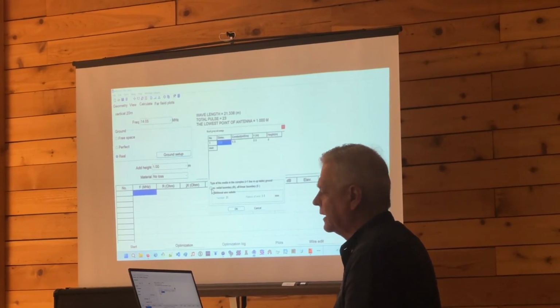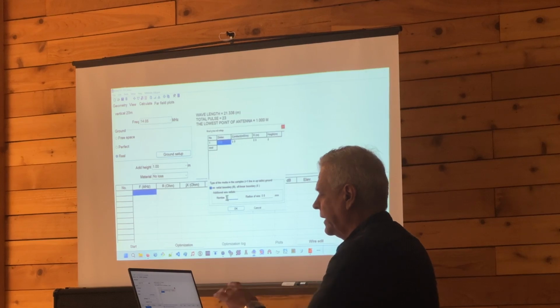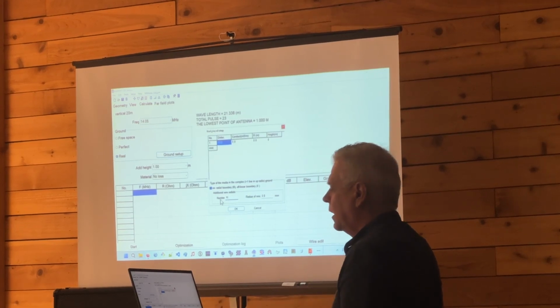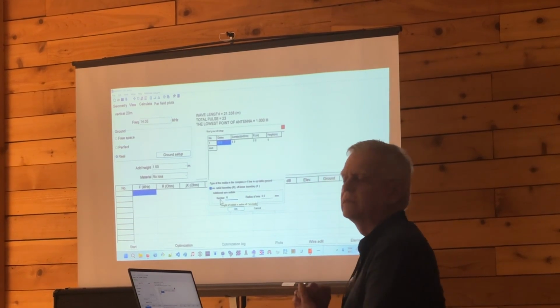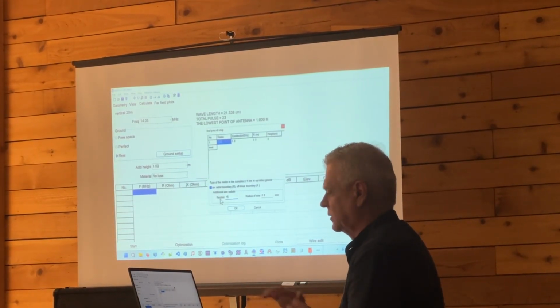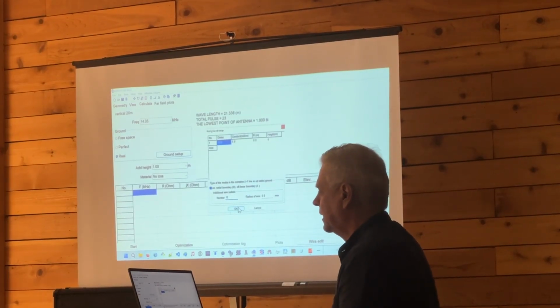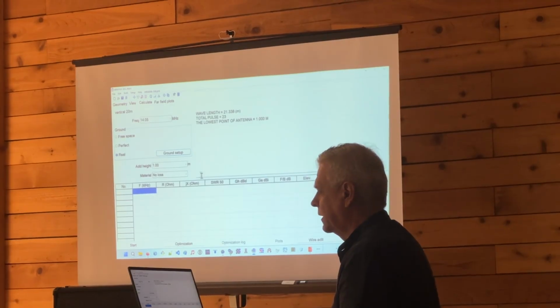For vertical antennas, we're going to click this box right here and say, consider radials. We're going to tell it they're going to be 11 radials, just to pick a number. One thing to notice is we're not telling it the length of the radials. We're avoiding that conversation here. There's nothing up the sleeves, just being transparent. Now we say okay, and we are good there.